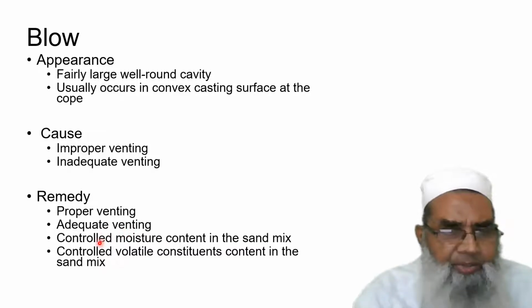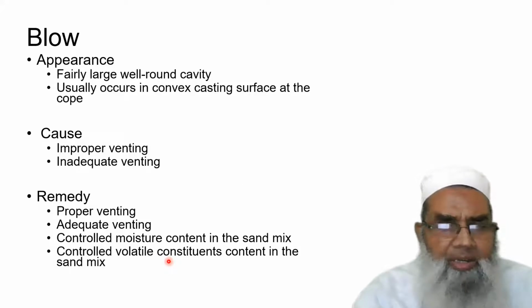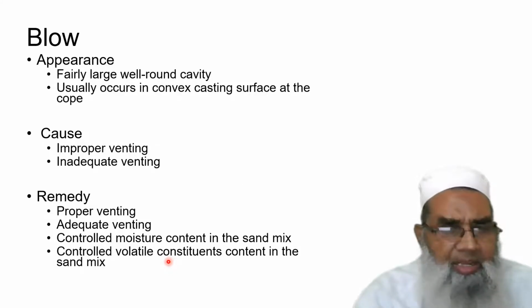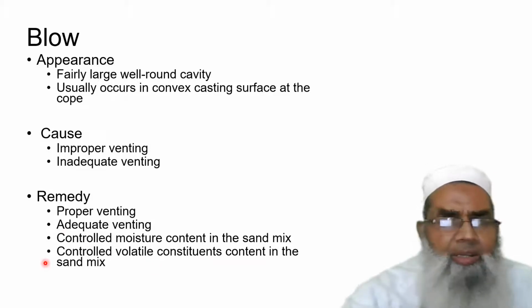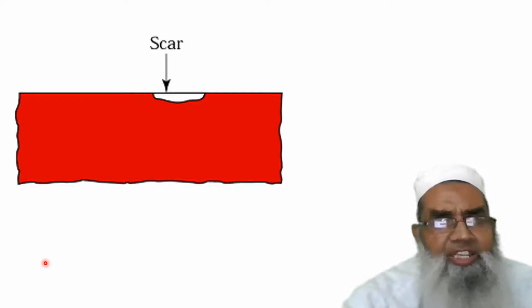We should try to control the moisture content in the sand mix and control the volatile constituents in the sand mix, so that they may not appear as a blow or blowhole.